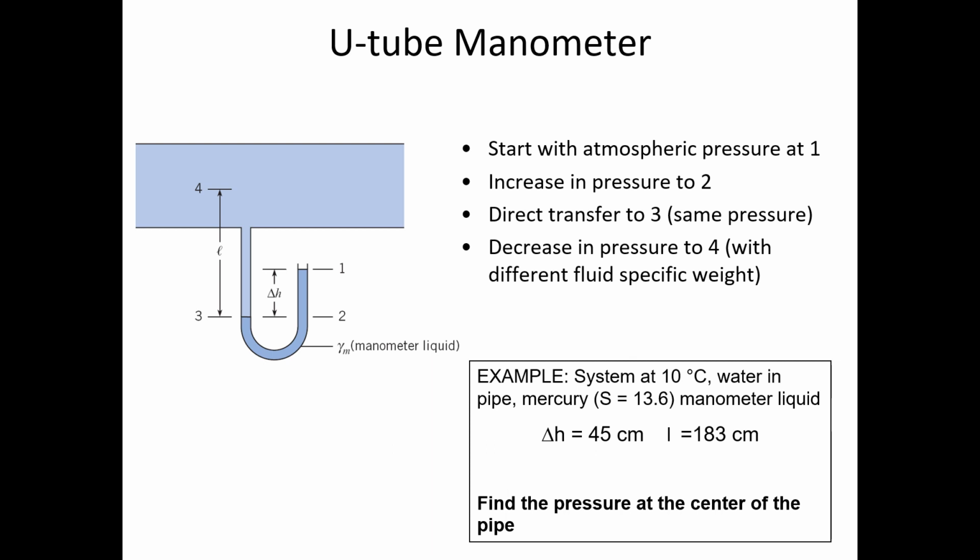And then let's do some of these preliminary calculations. The unit weight of water, because it's saying that water is flowing through the pipe, so let's use 9810 newtons per meter cubed as our unit weight of water. And then the unit weight of mercury, this is rounded off to 13.6. I told you earlier it's 13.56, but that's all right. We'll go with it. 13.6 times 9810 newtons per meter cubed.